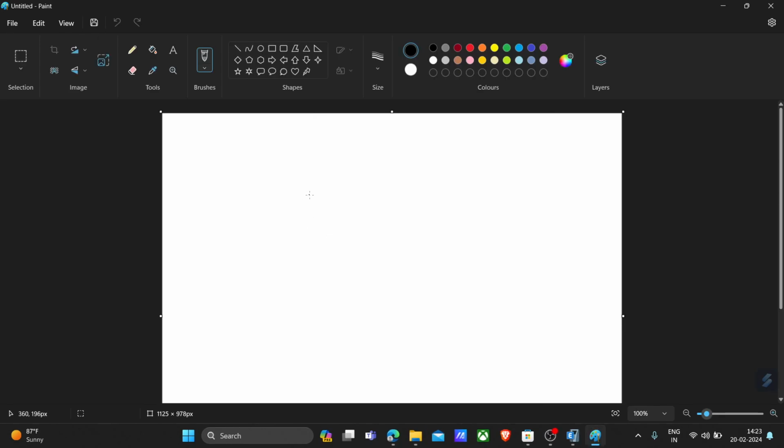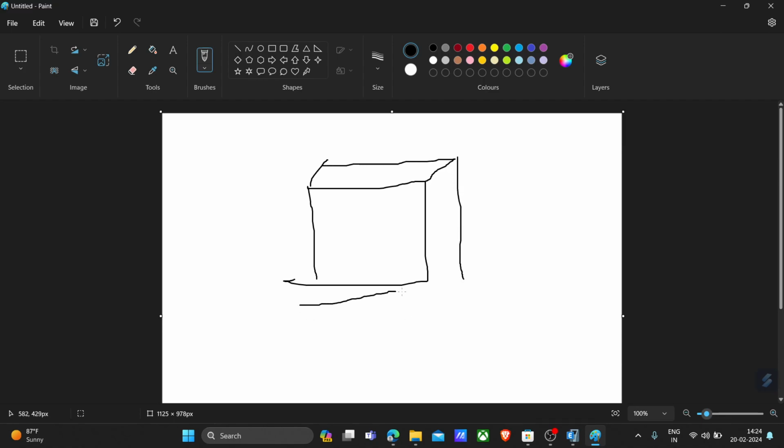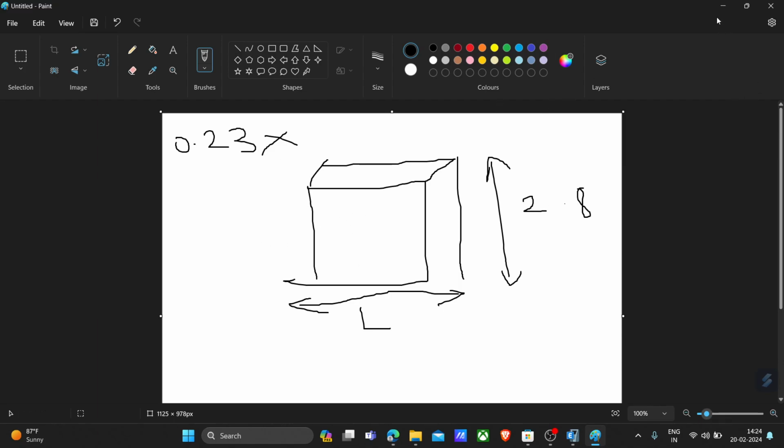So you see here, if this is your wall, right? Your wall will be like this. First you calculate the length here, at the bottom. Note the length. Suppose your length is around 4 meters, right? Then the height of the wall. The height of the wall is generally found by subtracting the beam on the top. We have given around 3 meters, right? So I will take around 2.8 meters for the height. Then the thickness is around 0.23, thickness of the wall. Next, the density of this masonry. Generally masonry wall density will be around 19 to 20.